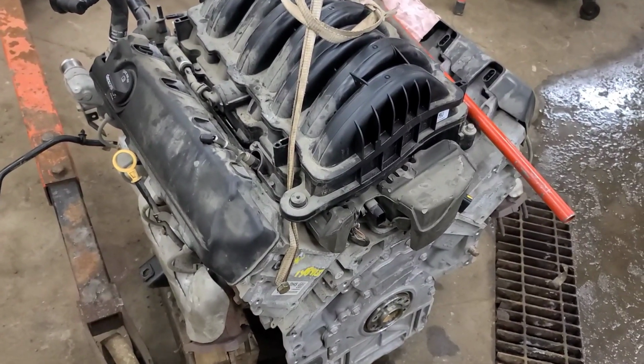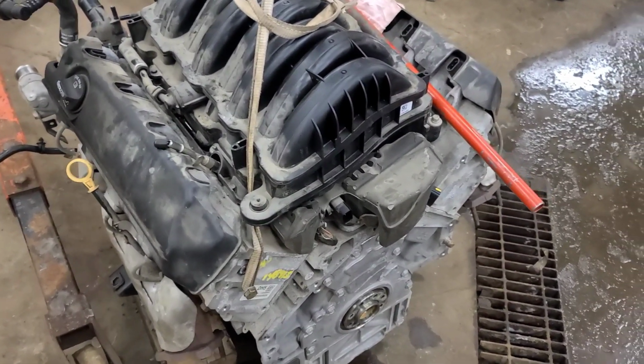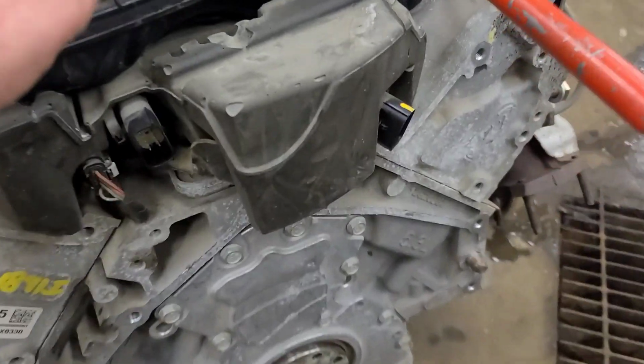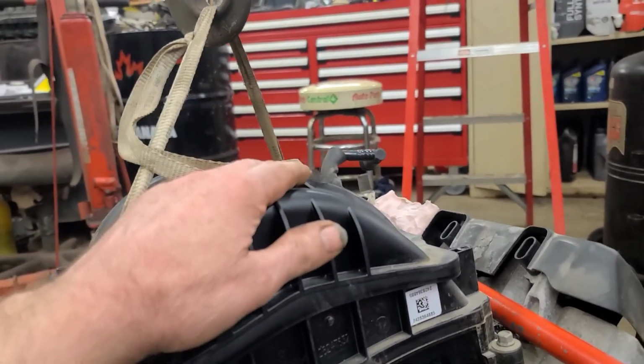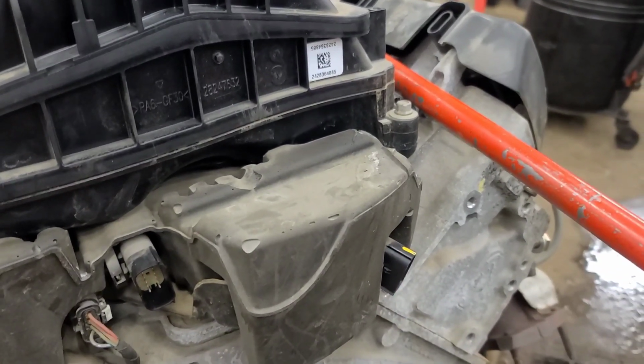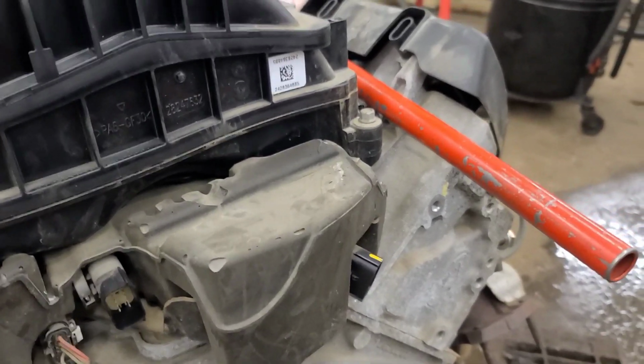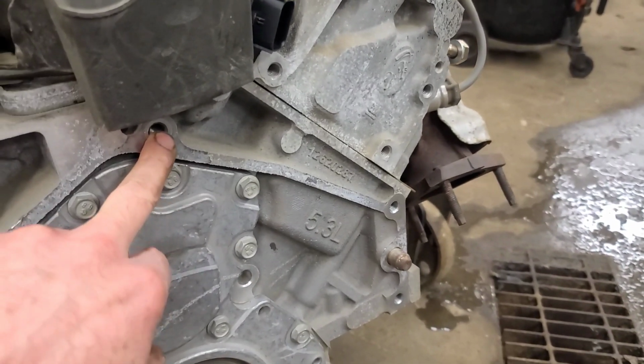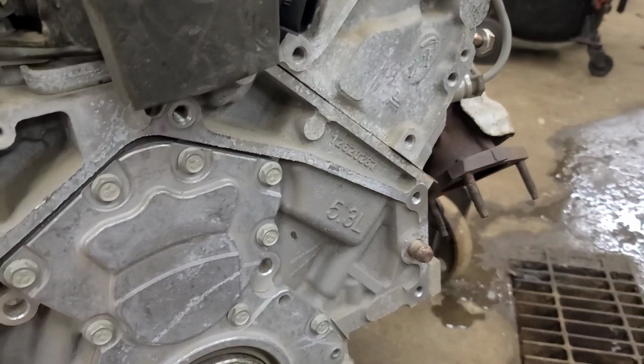Nevertheless, I think I'm going to pull the intake manifold off to put this in, because there's not a lot of room between the top of the intake and the firewall, and it's very difficult to get at these connectors back here. We need to leave the harness in the engine bay. Plus there's one bolt here that's next to impossible to get from underneath.